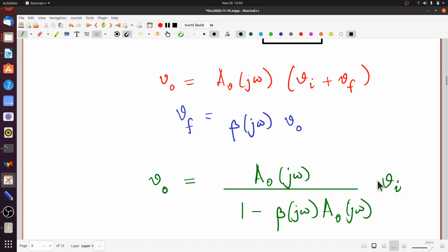So this is again something which is very, very similar to a result we had for negative feedback before. The only difference is there we had a plus sign here. And because of negative feedback, the gain went down. Here, on the other hand, the gain of an amplifier would go up. And that's sort of easily understandable. The output is feeding back and helping the input, so the output should be larger.